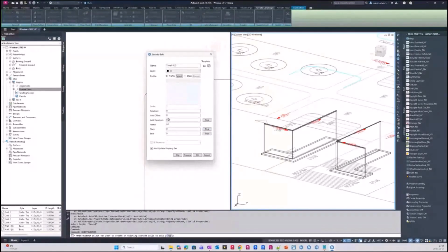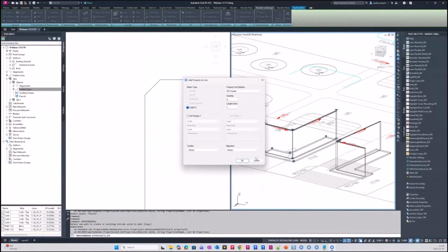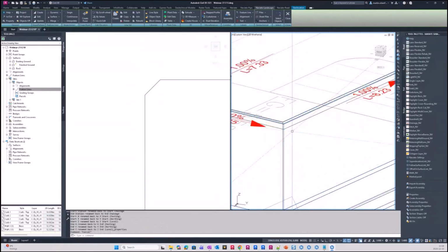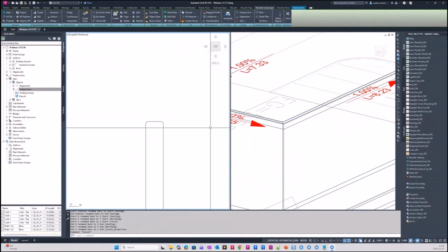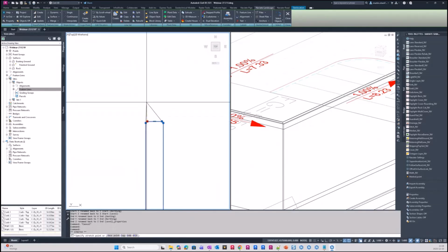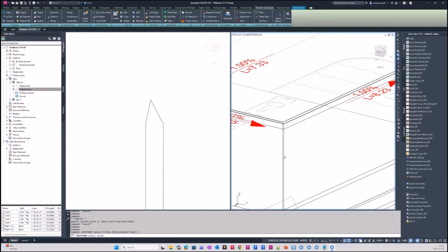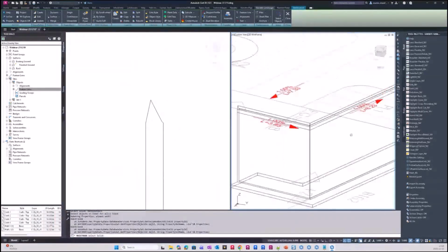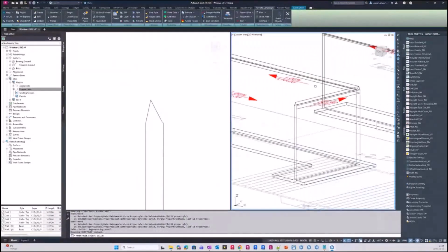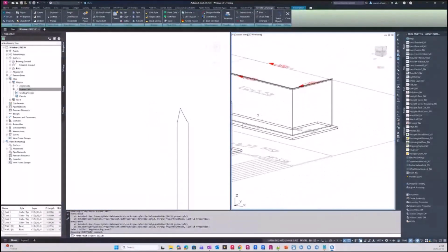So if I want to add 16 centimeters, I can just add it here and then hit OK. And it will update the wall. Same thing if I change my line, or if I change the profile, I can just do a ugly change here, like something like this, and we choose update solid and just hit solid. We can see that it updates after my new profile. We choose to not have this dynamic, so it won't update if you don't do it yourself.